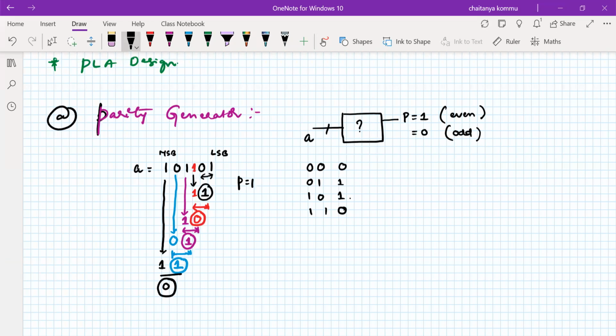So if I am performing the XOR operation, if an even number of ones are there, 0 has come. But actually our requirement is that 1 has to come. Okay, that means either you can take even number of ones as 0 and odd number of ones as 1, which is also possible. This is one choice. Otherwise, what we have to do is take the XNOR operation between them. Then if you use the XNOR operation, that possibility is there. Do you agree with me?